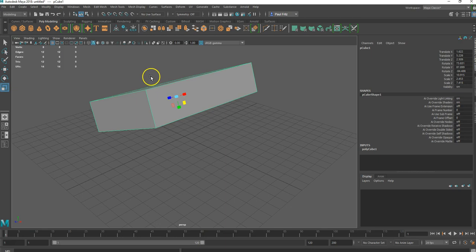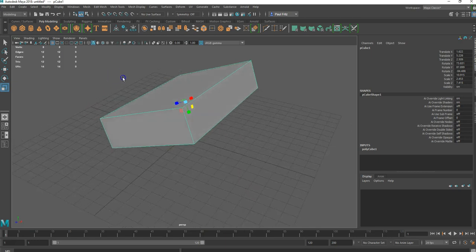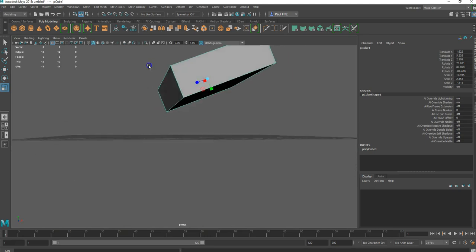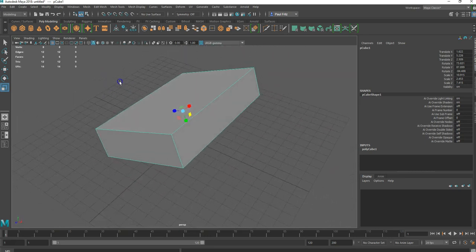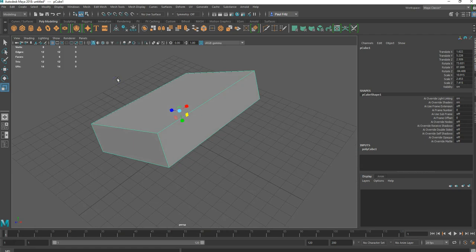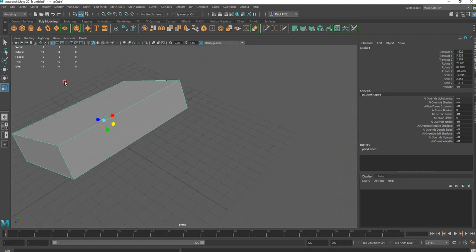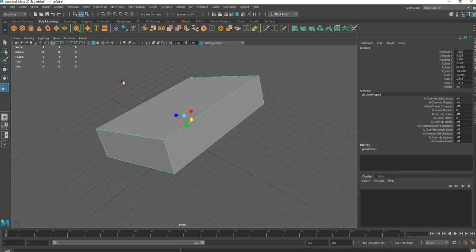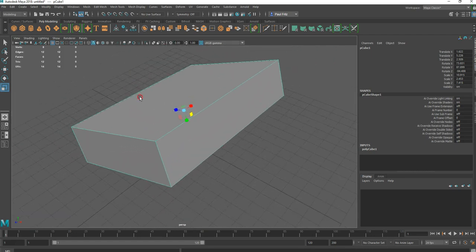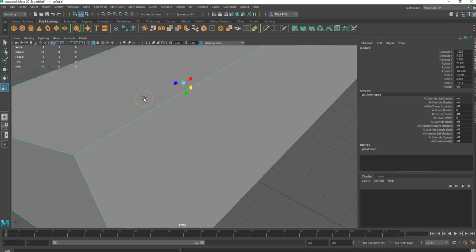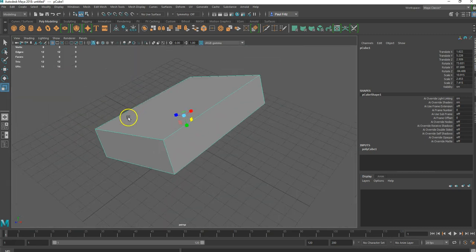But we still haven't talked about how to actually move in Maya. And the way to do that is if I hold the Alt key and then my left mouse button, I can now rotate my scene. So Alt and left mouse button. Alt key and the middle mouse button allows me to pan it around this way. And then Alt and my right mouse button allows me to zoom in and out like this. And also using the middle mouse button, if you have one that's a rotate button, you can rotate in and out, and it also allows you to zoom in and out.